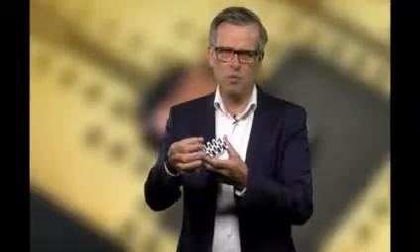There are also more modern horn antennas, used in systems like phased arrays. And this is an example of an open-ended waveguide, which is in fact a waveguide which at the end is open-ended. So you can also say it's a horn antenna. And these antennas are connected, as you can see, to what's called a transmit-receive module, where the electronics for transmitting and receiving the signals is being done.